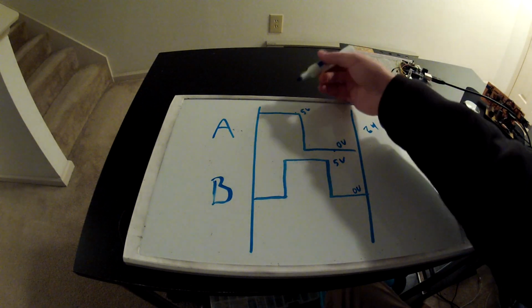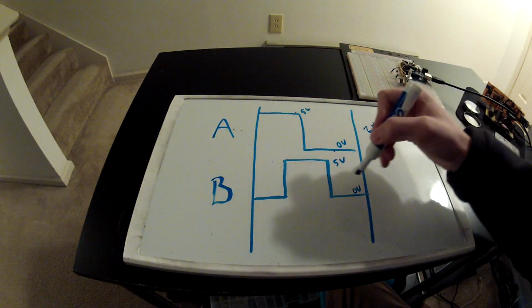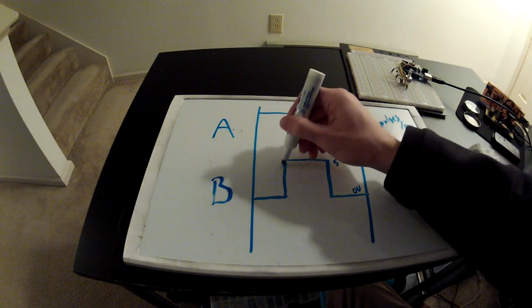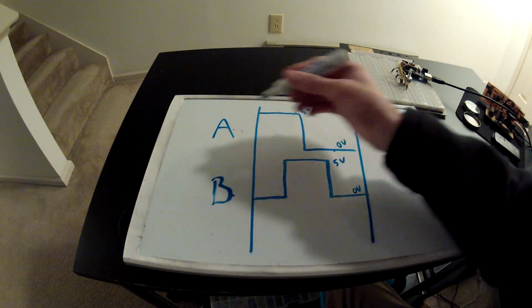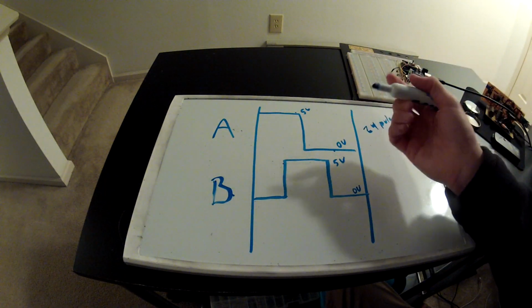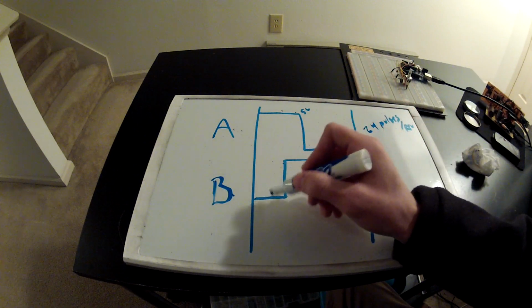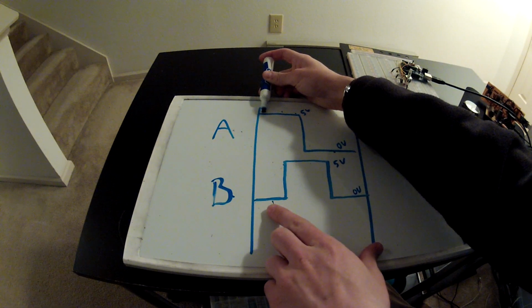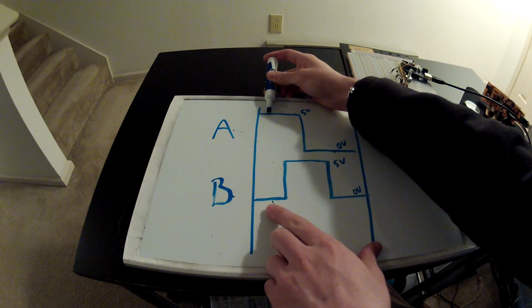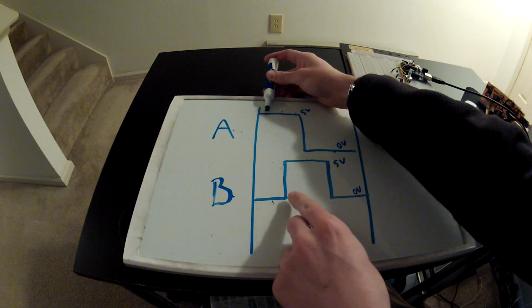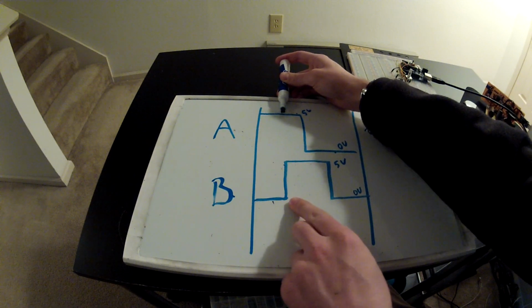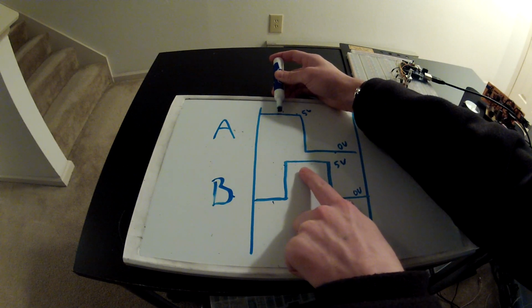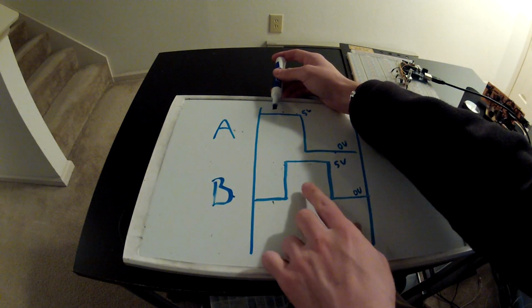All right, so let's say you're looking at all of these signals, and at any given point in time, as you're rotating it, only one of these signals, either A or B, will actually change states. You're not going to get an A change and a B change at the same time. So let's see, as you're rotating it, A signal is high, B signal is low. So you're rotating it one way now. All of a sudden you get a change on your B signal. B signal goes from 0 to high while A is high. That means you're rotating it forward. We know that. We'll put that in the code.